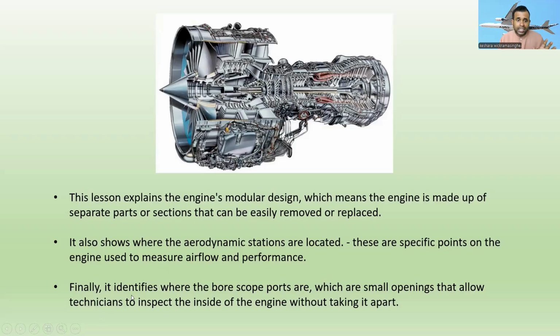Finally, it identifies where the Borescope ports are. Why do we use a Borescope? We use a Borescope to check what happened inside the engine, like cracks inside the compressor fan blades. If there is a crack, we cannot see it with the naked eye, so we have to use the Borescope. The Borescope ports are small openings that allow technicians to inspect the inside of the engine without taking it apart.